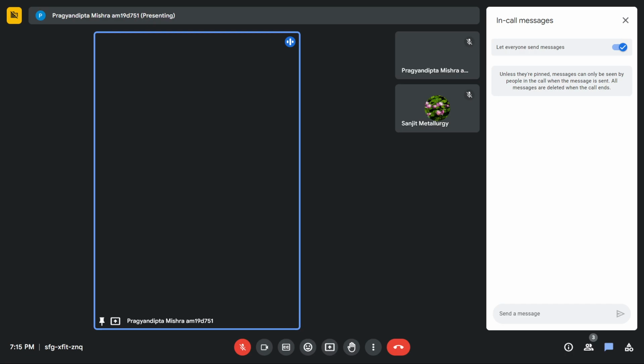So your change in volume by original volume is equal to the volumetric strain. Okay, this is your change in volume by original volume, which is the volumetric strain, and then the volumetric stress. Let's say that it's P because it's pressure, right? Okay, not this P. Yeah, this is equal to K times volumetric strain.